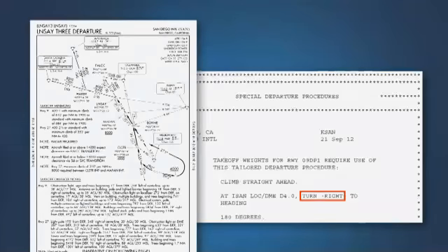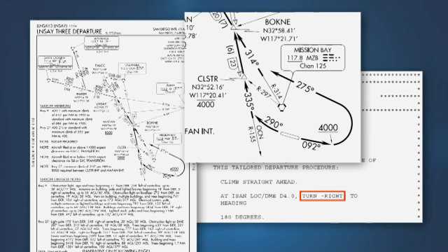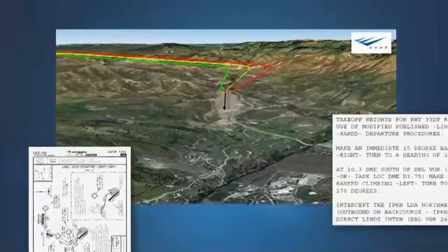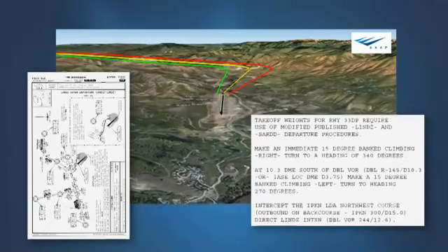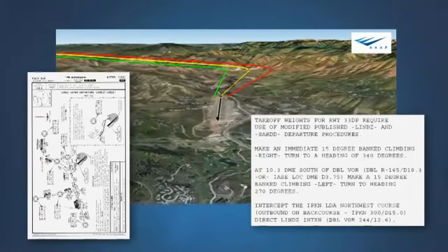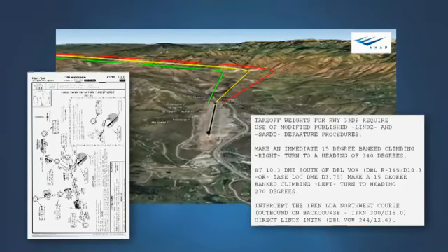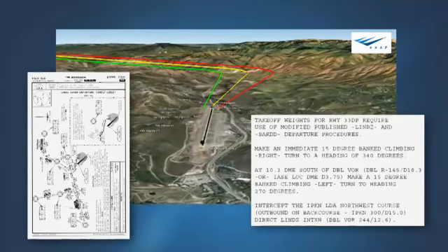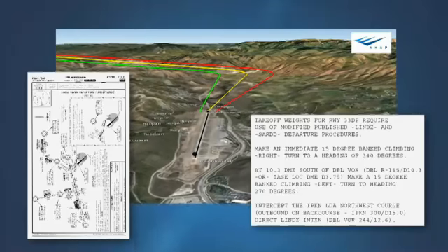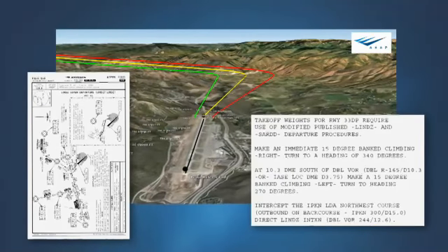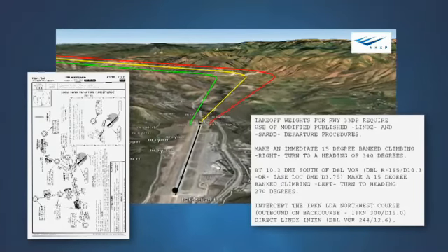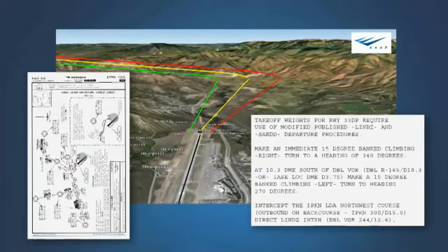The question of what action a pilot should consider or take when the engine failure procedure differs from the IFR departure procedure is worth addressing. At terrain-challenging airports like Aspen, the engine failure procedure typically conforms to the IFR departure procedure for the takeoff runway. However, modifications may be necessary to identify the start of any turns using precise geographical references instead of the altitude crossings that are frequently used on SIDs and ODPs.